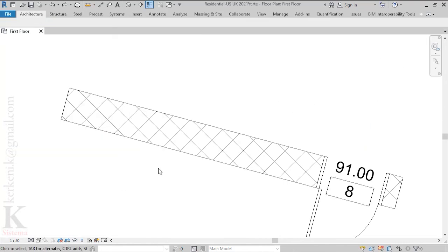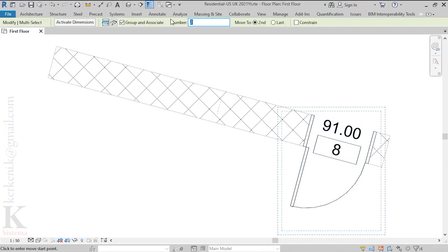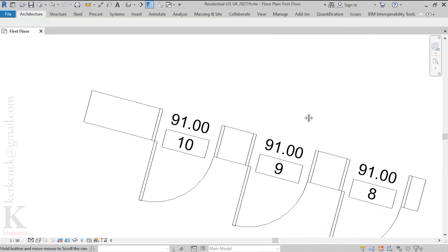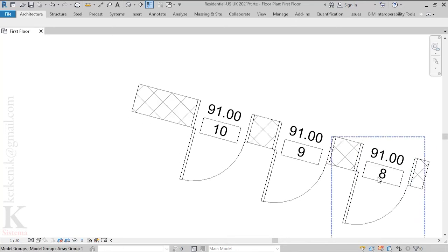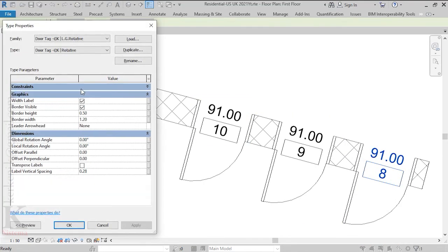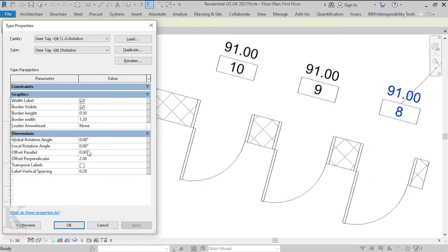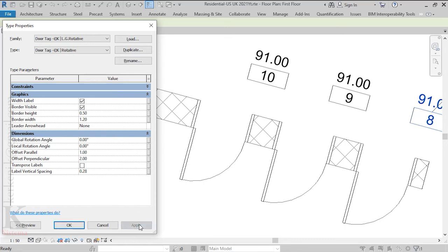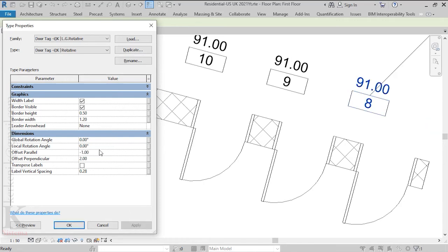Before I go through other parameters, I'm going to undo the change and create an array of tagged doors. Okay, so for some reason, after finishing placing tags, you decide to offset them. Instead of manually achieving this like we normally do, just select one instance and shift them in bulk. It's very time saving when handling tens or hundreds of tags.